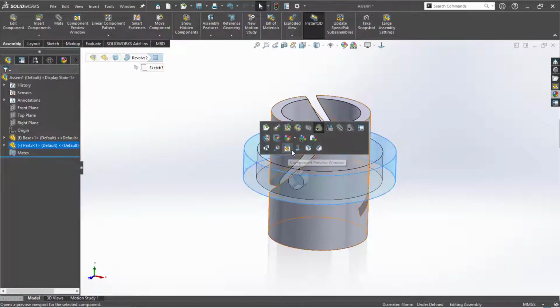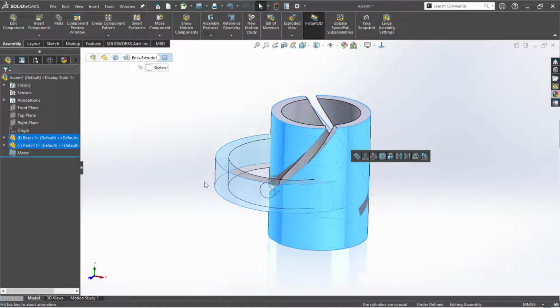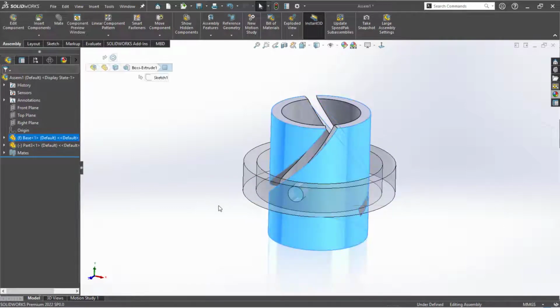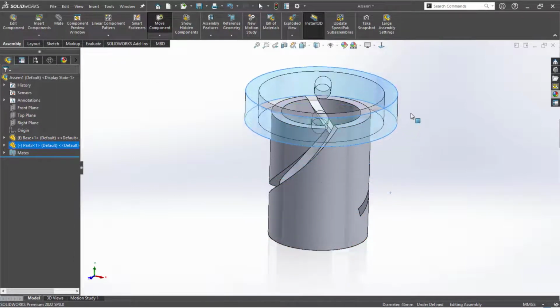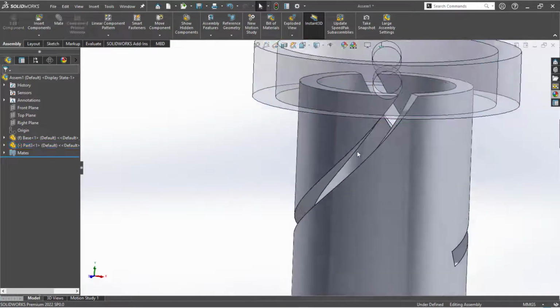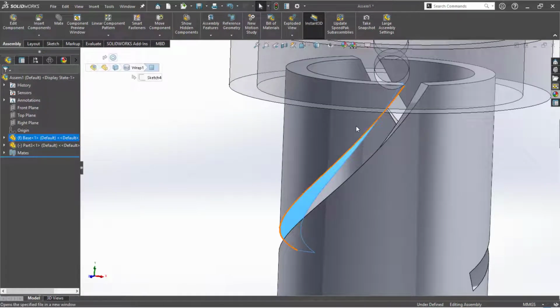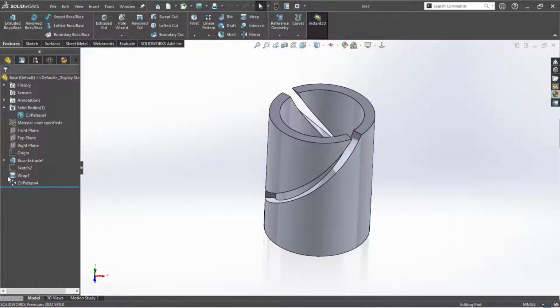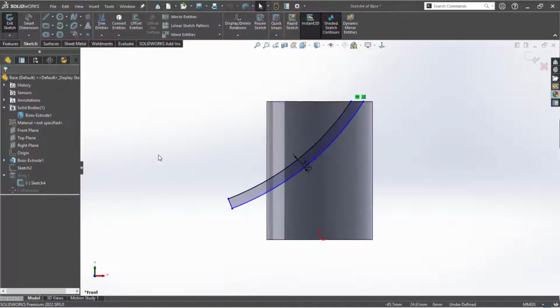So as I said, the diameter is 5, concentric relation. So once I pick it up, it won't fit properly. What I'll do is I'll change the values of it. There should be offset 5. Go inside, edit the sketch, double click on it, and change it. Now this is fine, right?